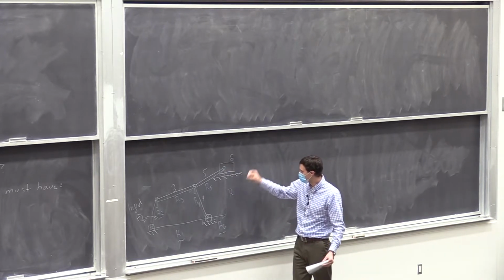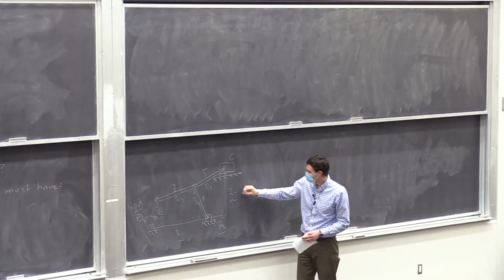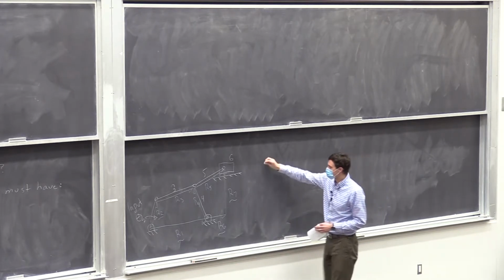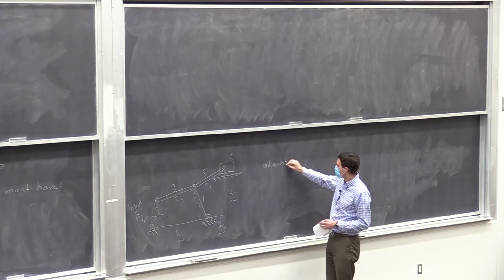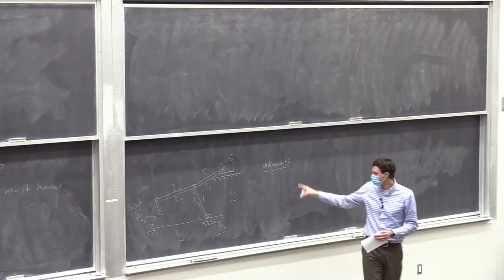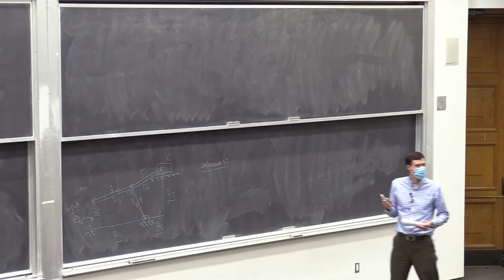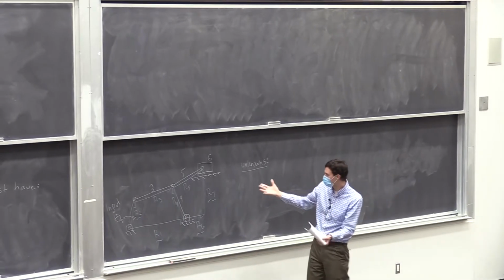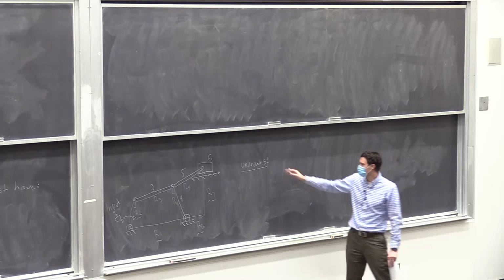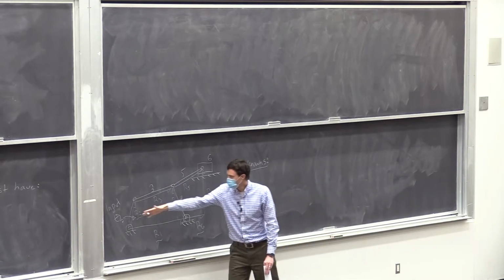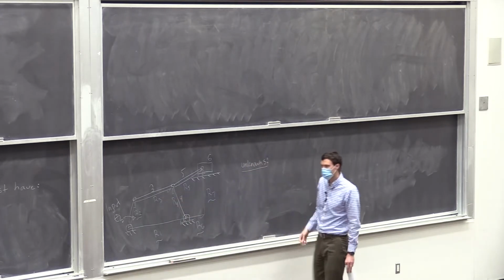Okay, and I'll call this R7. The height is a constant. So let's list all of our unknowns. Every one of these vectors, we have 7, and those should be able to describe the problem. They capture every element of the motion. So some combination of those in 1 or 2 loops should be able to solve it. Let's list out what we don't know. R2 is our input, so that doesn't count. R3 and R4 have constant length, but their angles are changing.